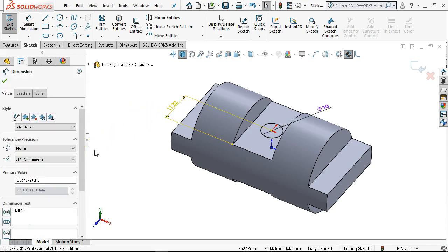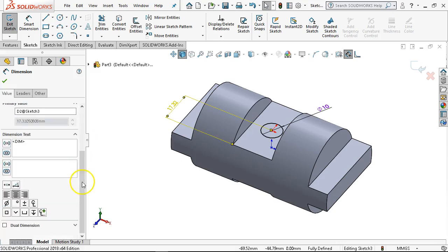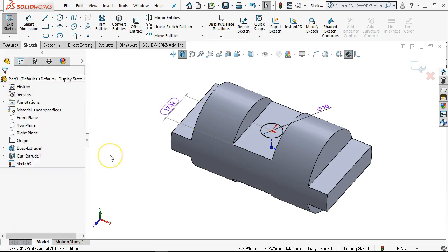My design intent, my best practices says that ought to be on center so that I can make it in any orientation. Why do I need a left and right part? If it needs to be a left and right part and I can get away with a slot, why didn't I make it a slot? Go through that thought process of what are the contingencies so that on the manufacturing side, I don't have to have special setups. I can indicate off of this edge, run those positions, whatever little fixture comes back on center, and we're okay. So this comes back to one of those, yes, I would like that to have an oblong or something around it that says, let's check that out.